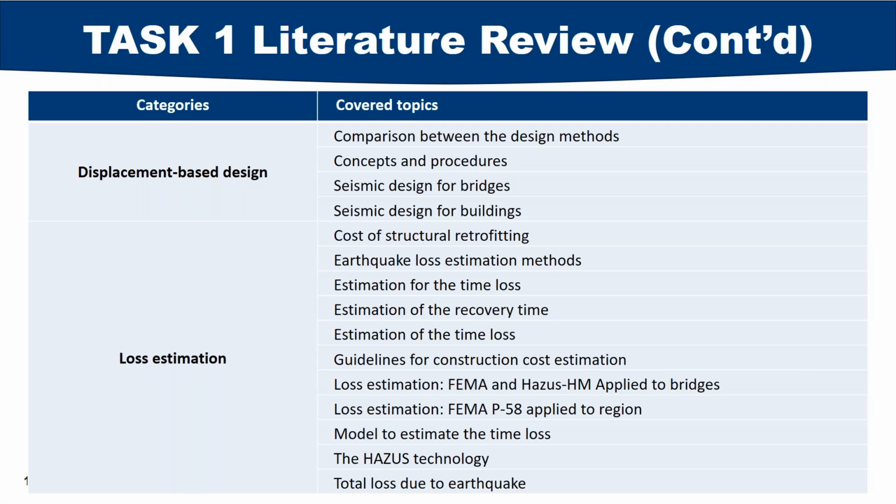Displacement-based design. And this is the origin, I would say, of performance-based design, where people start switching from force to displacement-based design, or use displacement-based design to complement force-based design. We found that displacement-based design is more appropriate for a lot of design categories, like seismic design specifically, or retrofitting, and this is what emerged later into resilient-based design.